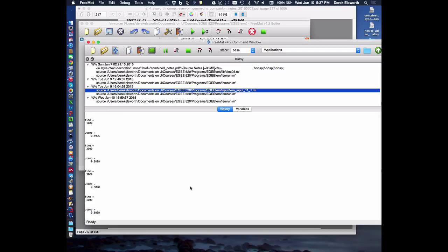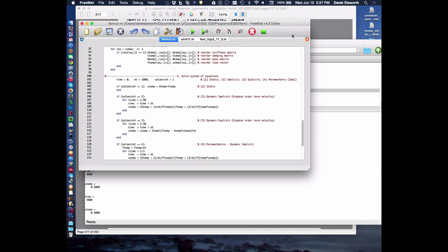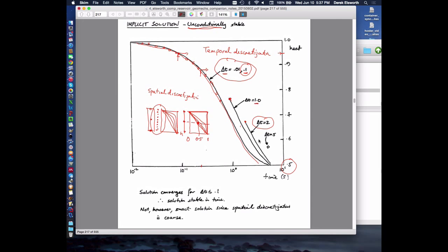But remember, be cautioned by what we talked about, discretization. And it's probably useful to revisit that. And I guess it was shown by this. Unconditionally stable means that it will always give you a result that probably approaches a steady state, which it does in this thing after running it. Because after 1,000 seconds, it should really be a steady state. So it gravitates towards that. But the steady state result it gives, although it's kind of correct for the steady state, it's actually not correct for the time steps, because it actually would have reached steady state much before that, in many respects.